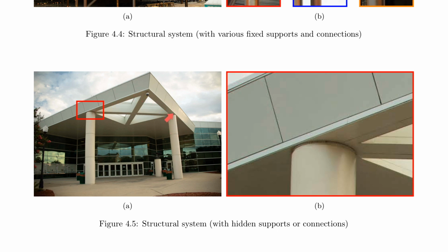And it also helps to support the roof from here to here. So it's an entire structural system, but that structural system definitely has a connection and a support reaction up here for this roof. And my best guess here, I cannot see inside, but my best guess is that it's also a fixed connection, but we really would have to go and dig into it to really see what's going on.